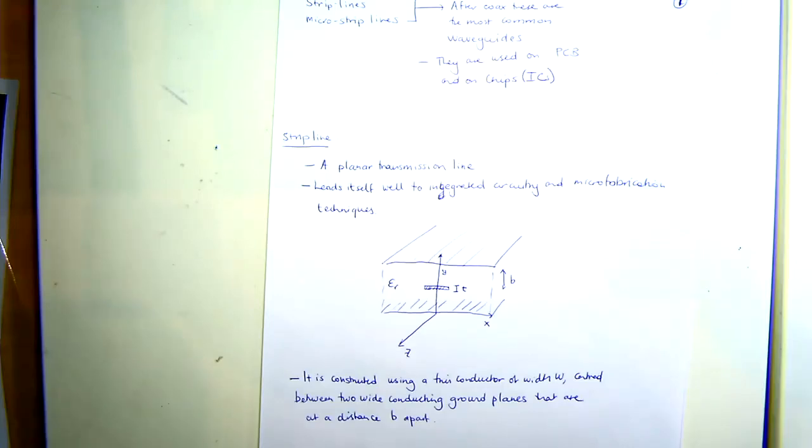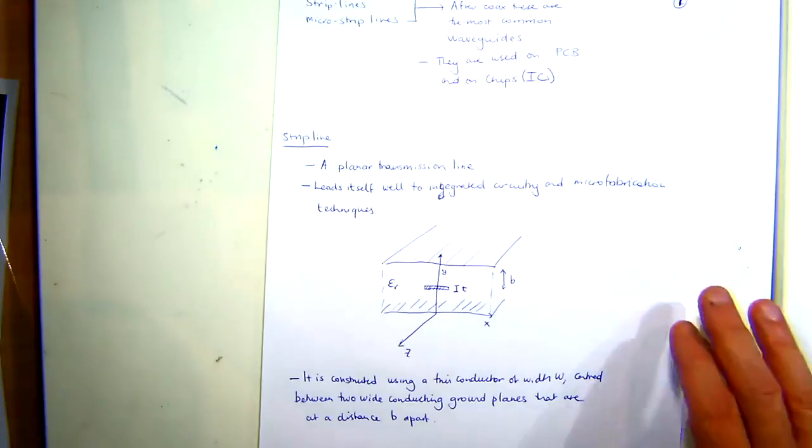And you just have to know about them. Now, why am I talking about coaxial cables? Well, other than we've done it in the past, you don't make coaxial cables. You just go buy a coaxial cable, right? Whereas if you're actually building a PCB board, you need to be able to, depending on the distance between layers, the thickness of the metals, the dielectric constant, the loss tangents. All that has to come into it when you're actually designing it. And we'll go through this today.